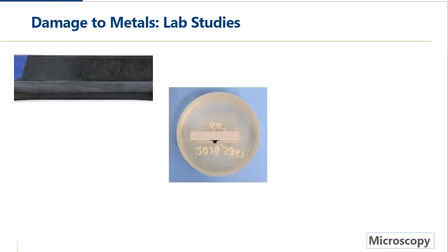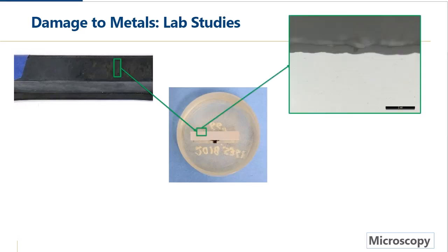So we prepared what's called a polished cross-section. In this case, we cut a piece, we embed it in that circular puck of resin. That's just to make it easy to polish a very smooth surface so we can look at it in great detail in the microscope. So if we take a sample and then just look at that surface, we're not looking at the aluminum so much as we're looking at that anodic coating. And you can see that micrograph up there at the top.